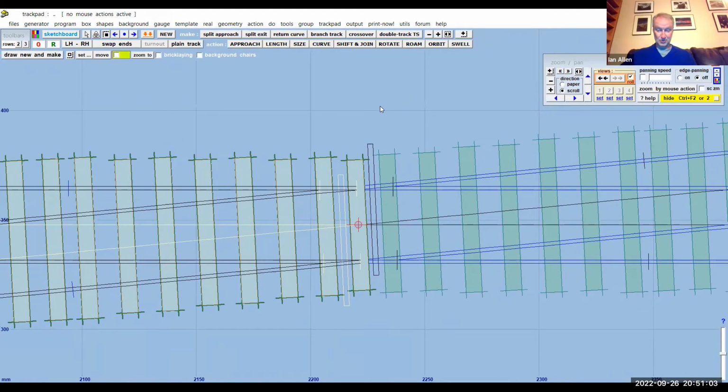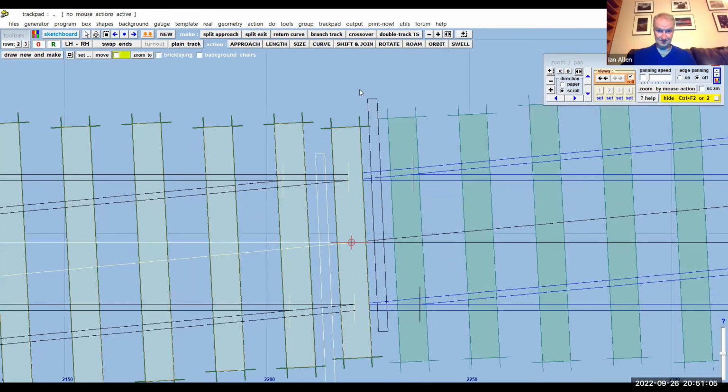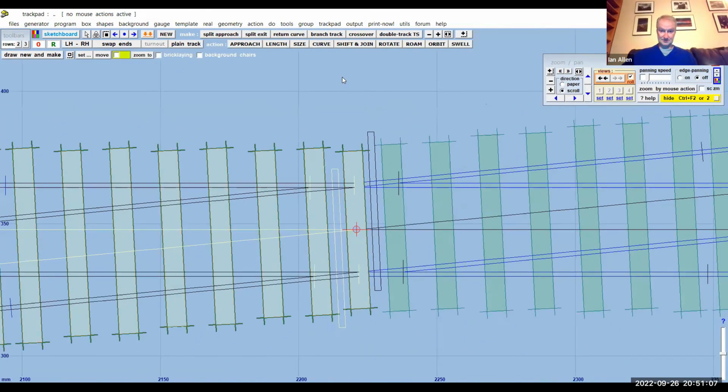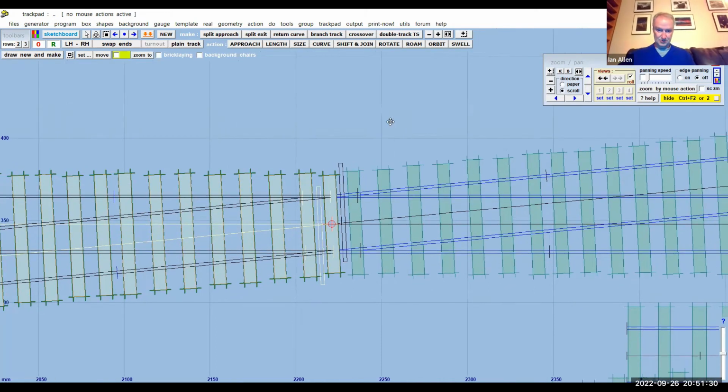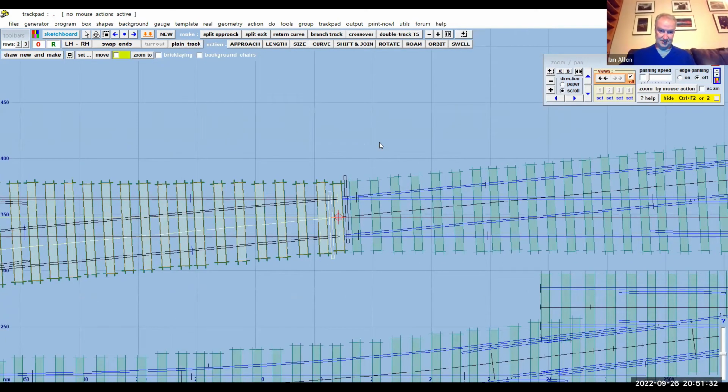And this has got switched blades because it's a shallow angle. So anything normally, we touched on this last time. I know Martin and I were chatting about it, and Martin mentioned that obviously if you've got a diamond crossing on a curve, the angle that you would use switched diamond blades on gets tighter, so the number reduces. But normally on straight track, anything above a 1 in 8, you would use a switched diamond for the K crossings.